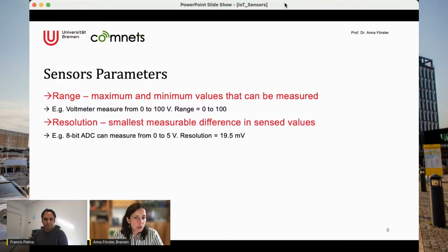There is also the so-called resolution. How exact and precise is the value? Are we talking about 0.something or about 0.00something? This is very important for some applications. Sometimes you don't really need it because you're happy with anything. For example, for water content in the soil for agricultural applications, it's more or less enough not even to have a decimal there, but you still need to understand what your resolution is.